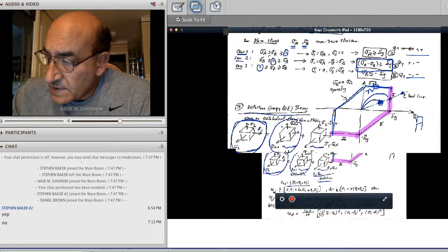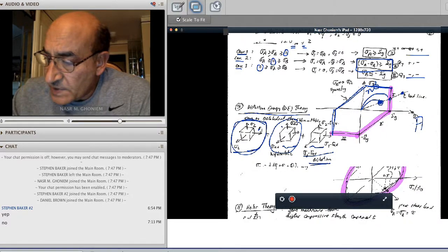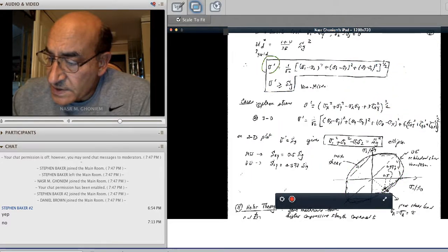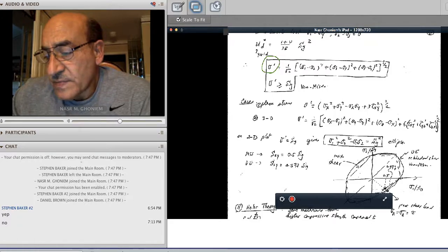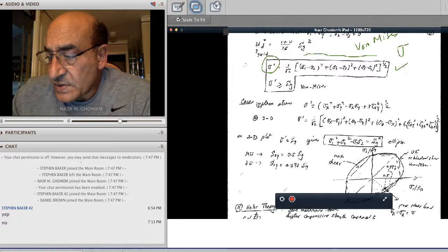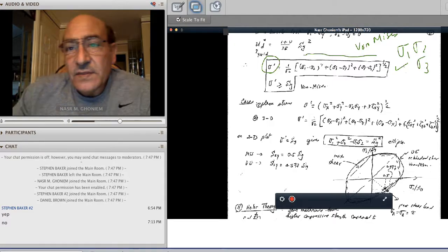And the end result of this is that we found a representative stress, which is given by this formula. And this representative stress, we're going to call it the von Mises stress. So this is the original way that you find the von Mises stress if you know sigma 1, sigma 2, and sigma 3.